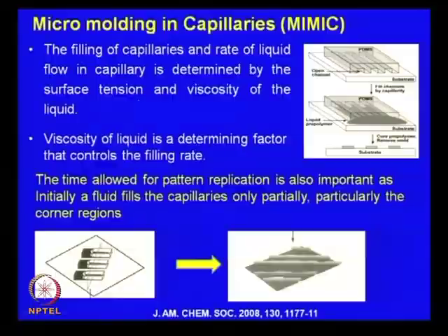So, in order to ensure good capillary driven flow, or good channel filling driven by capillarity, you might have to ensure that the surface energy of the stamp walls is slightly higher, so that you have a significant amount of driving force. How that is tailored, I think we will discuss in one of the subsequent slides. So, that is essentially the role of surface tension over here.